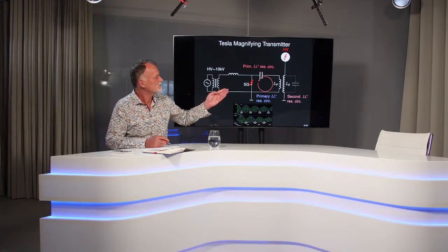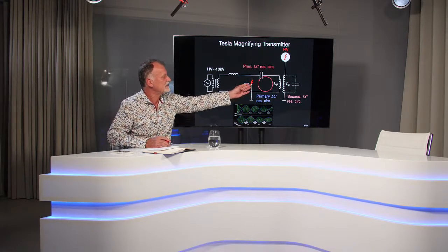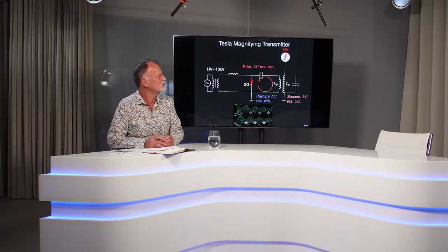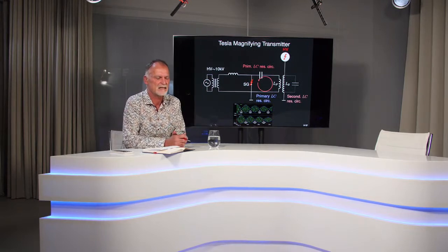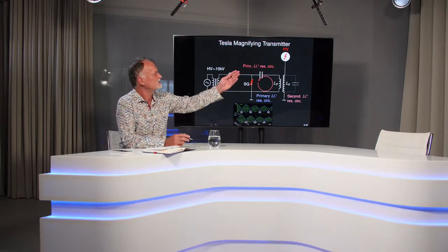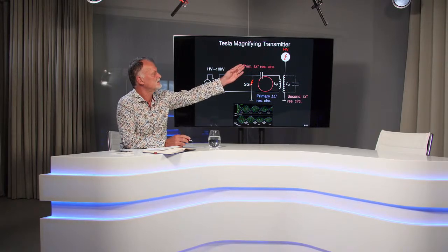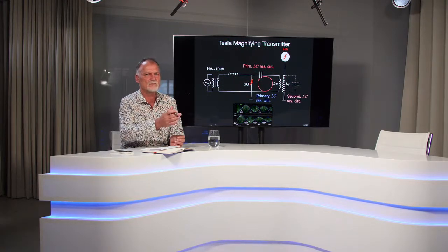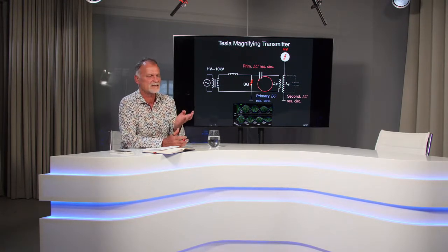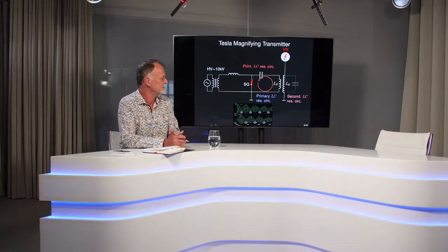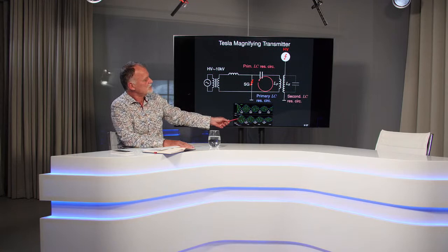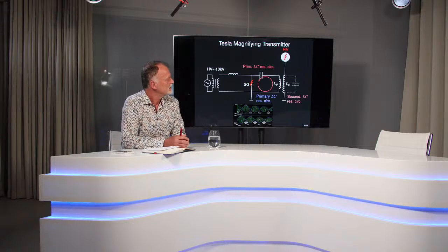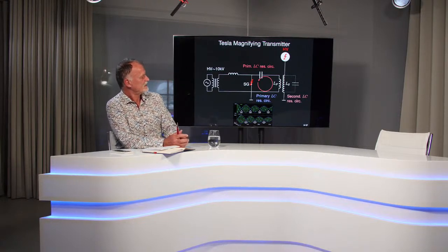Usually if the energy is transferred to the secondary circuit, there is an electrode at the high voltage end of the Tesla transformer, and usually what happens is that the huge tension on the hot end of the Tesla transformer will break through the air, and you will observe the discharge, and the energy is wasted in the discharge. But if not, then you usually see this kind of beating between the primary and secondary circuits. Very good. So we can go to next slide, I believe. Right.